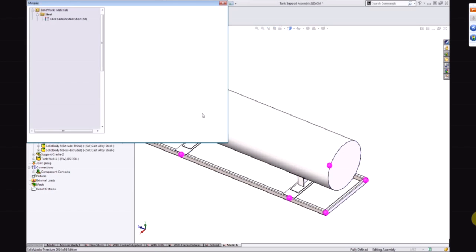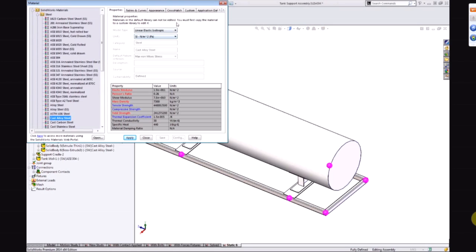If you want to modify that, you certainly are able to. And the best way to do that is just to right-click and go Apply Edit Material. One thing you'll notice is if you look in the SOLIDWORKS Materials library, nothing in here is editable. Right? I can't click and I can't modify, and that is by design.